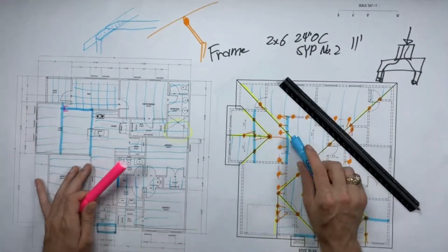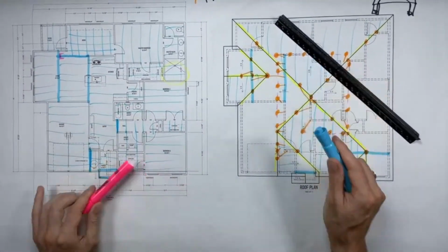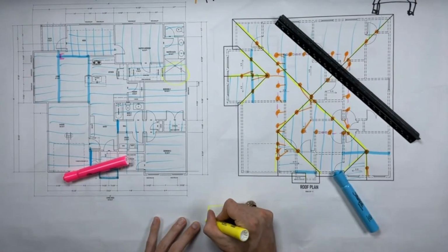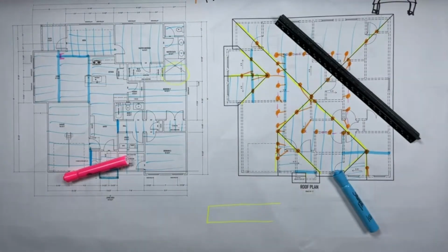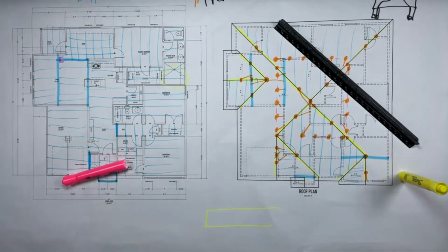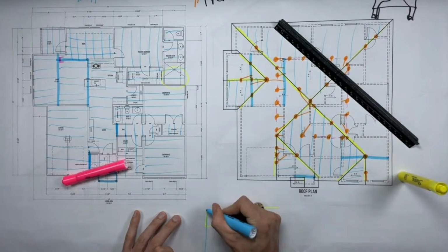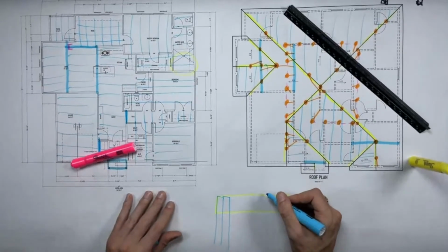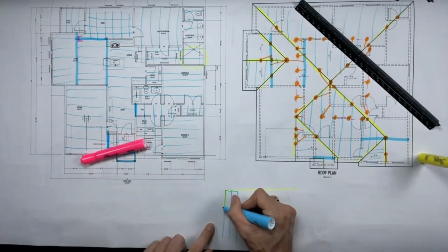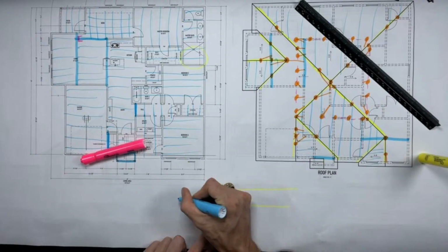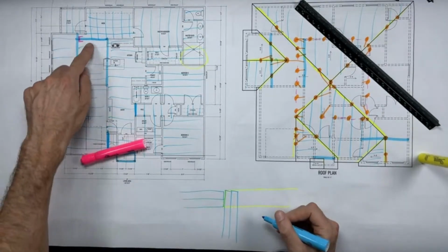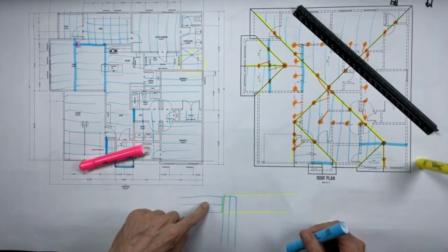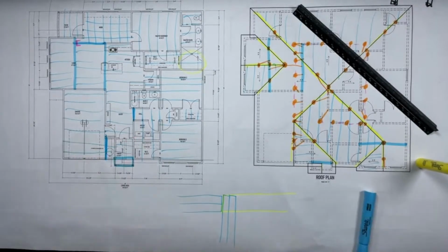Okay, so let's look top down and imagine this scenario right down here. So top down, here is the wall framing. It stops, goes this way. And that beam's probably going to be some LVL or something. So let's say it's 2 plies of LVL. So there's your beam, and it lands on the end of the wall. And I have another beam that's also 2 plies of LVL, which would be ridiculous for that size. It's probably not, but that's the situation I have. How do I hold up this beam if I have no wall left? The only way to do that is by using a hanger.